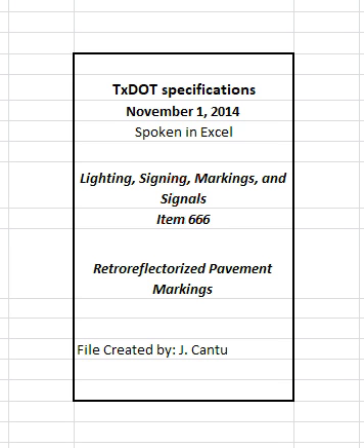It must place solid and broken lines simultaneously, and white line from both sides. Lines must have clean edges, a uniform cross-section with a tolerance of plus or minus 1/8 inch per 4 inches of width, uniform thickness, and reasonably square ends. Skip lines must be between 10 and 10.5 feet, with a stripe to gap ratio of 10 to 30, and a stripe gap cycle between 39.5 feet and 40.5 feet, automatically.